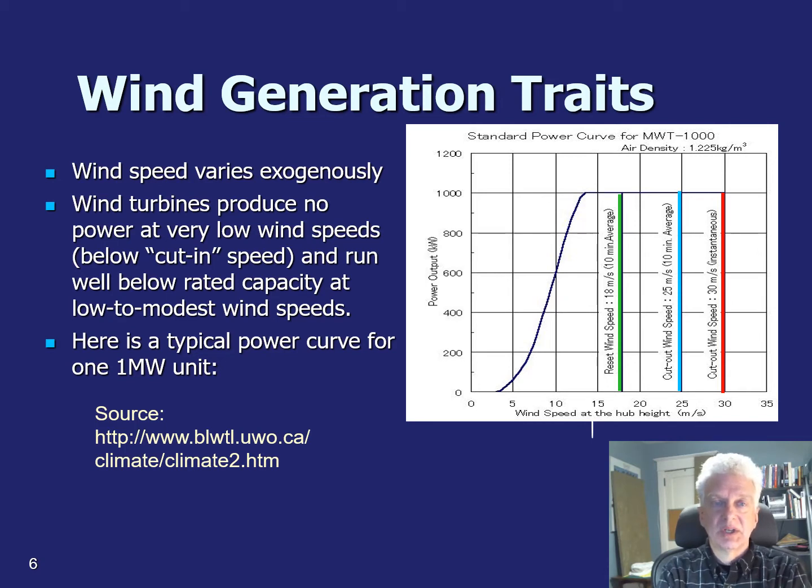As the wind increases, you can see there's a nice exponential increase in the torque that you're getting and the power you can produce. And then you begin approaching past 10 meters per second. That S-curve turns to level off at the rated capacity of the turbine. So you have more torque after about 12 meters per second than the system can extract, and you're just limited by the capacity of the generator unit inside it. And then from 13 meters per second on up, the unit tops out. No matter how much more the wind blows, it doesn't get any more powerful. It's just producing its rated capacity.